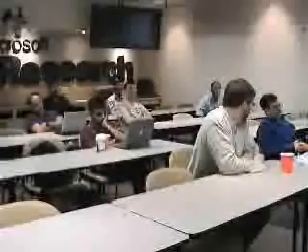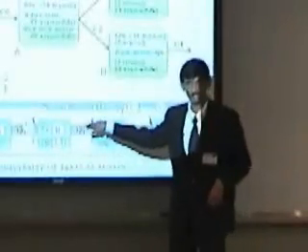Wow, and so these are just registers which will allow... The packet out of global memory doesn't swamp the savings you get from communicating on the next neighbor channel? Sorry? I mean, it seems like if A has to manipulate the packet out of global shared memory and B has to talk to global shared memory, then the little tiny savings you get from passing the handle across the next neighbor channel would be swamped by the fact that B found out about the packet right away, but still had to go load it out of global shared memory. Mm-hmm. So that's actually correct in this particular hardware.